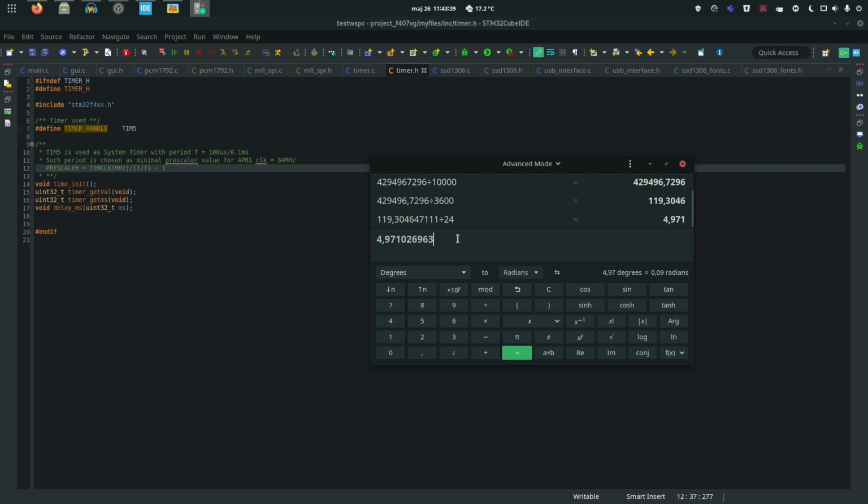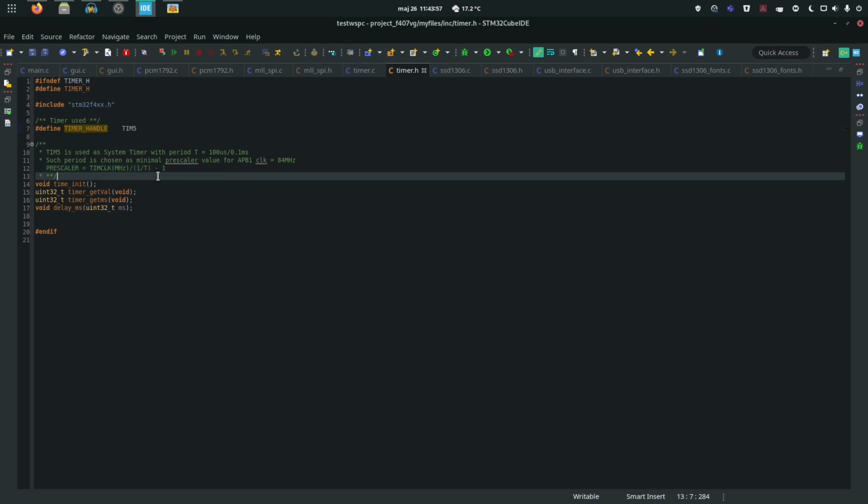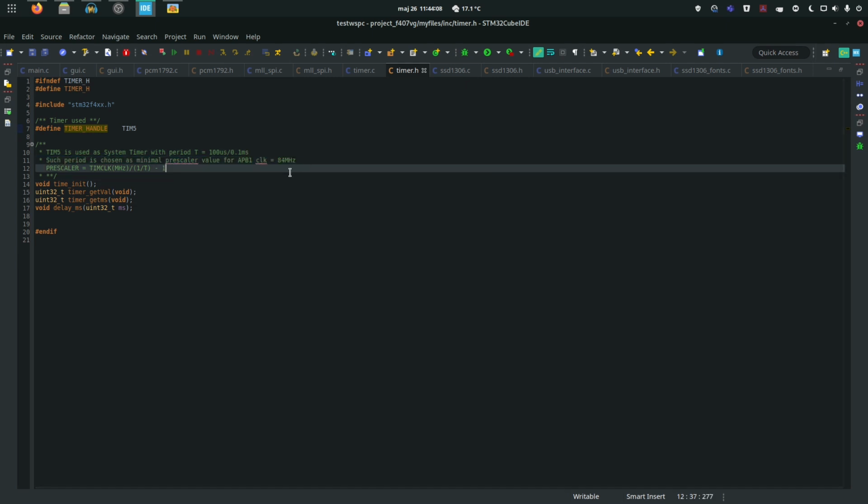So this timer could run without being restarted or overflowing for 5 days, and I think I would run this DAC for 1 day maximum and not just continuously turned on. Therefore 5 days is more than adequate. Now you might think, why am I using a special timer and not a global variable with an interrupt to increment some kind of global variable for the current millis? And I could use any timer with any kind of prescale to tick at exactly 1 millisecond.